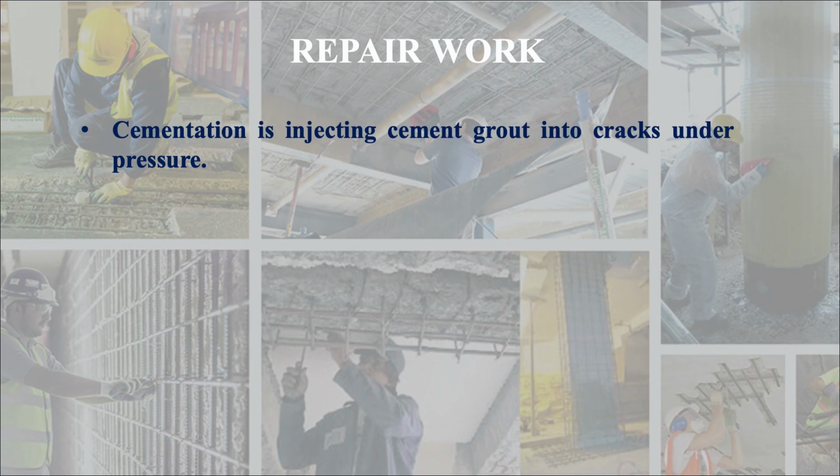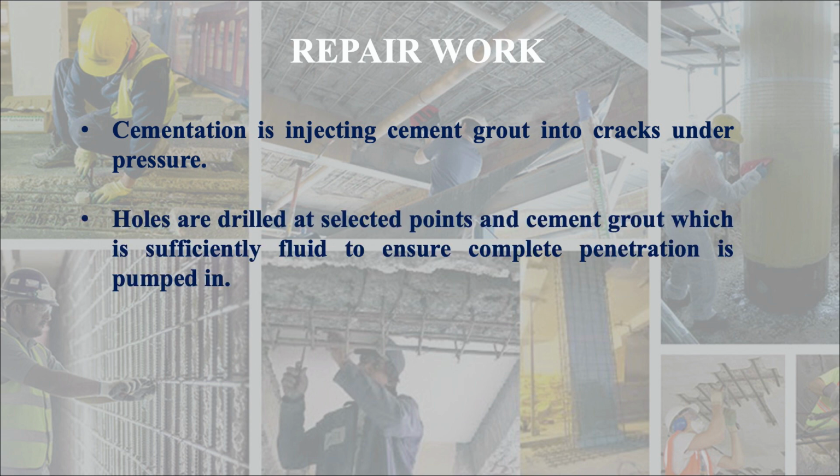Cementation is injecting cement grout into cracks under pressure. Holes are drilled at selected points and cement grout, which is sufficiently fluid to ensure complete penetration, is pumped in.